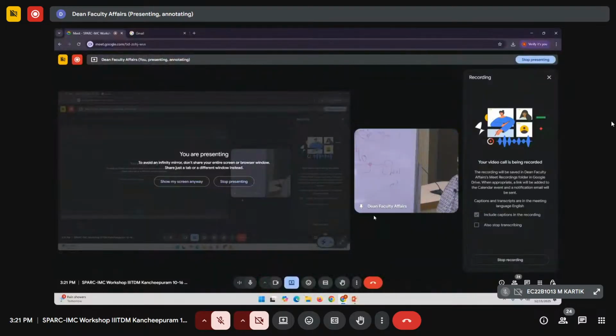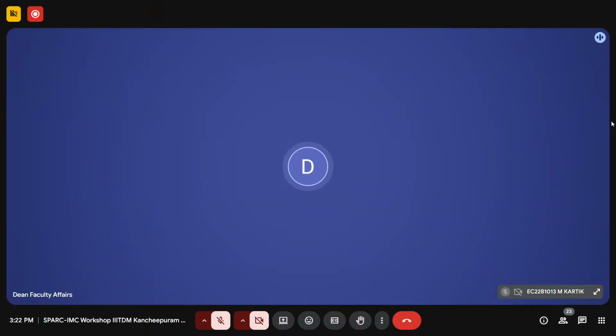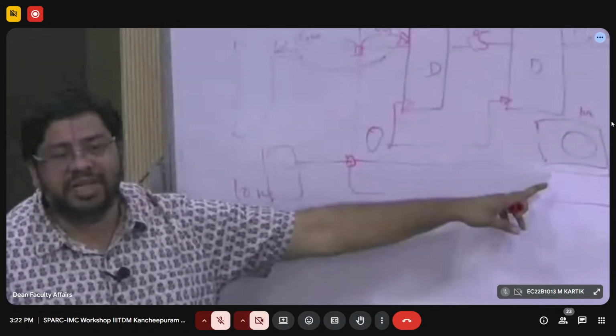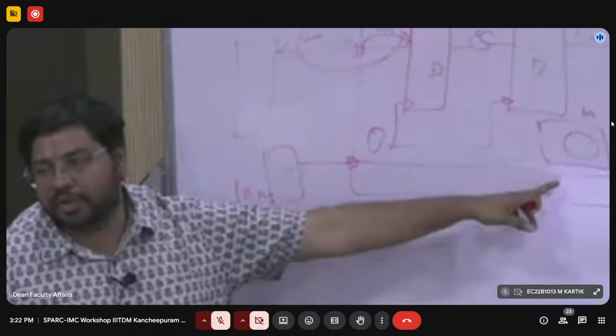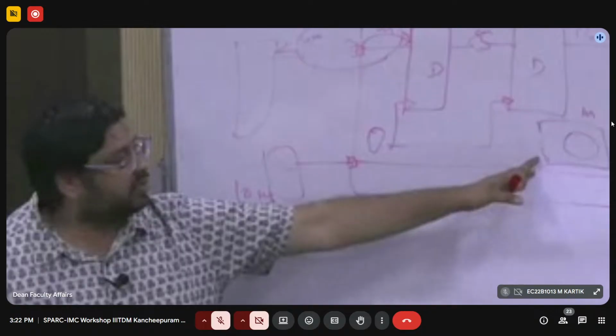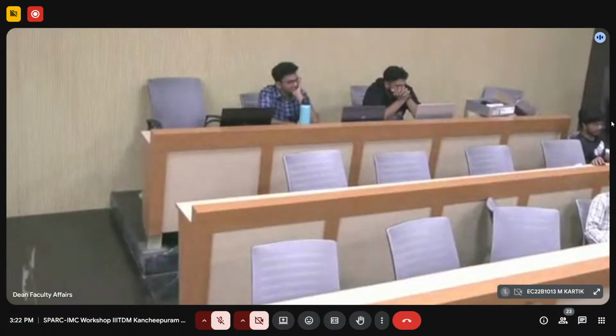If the chip is on, it's just going to work for 10 minutes, whereas other modules will work for like 80 minutes, right? So if it is just going to work for 10 minutes, then I'm going to shut this off. I'm not going to supply the clock for this. After 10 minutes, I'll shut the clock off for this particular module, right? So how do I do this? Simple AND gate, right? You know the function of an AND gate?